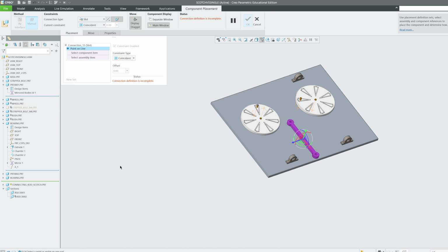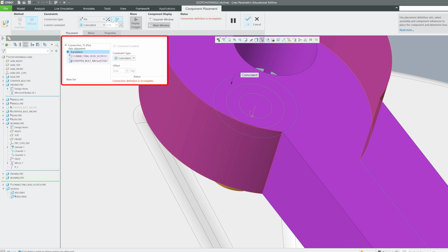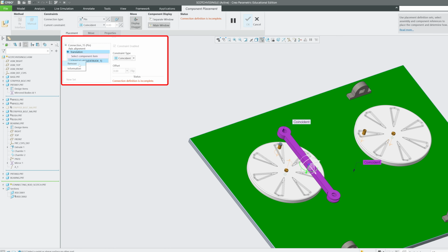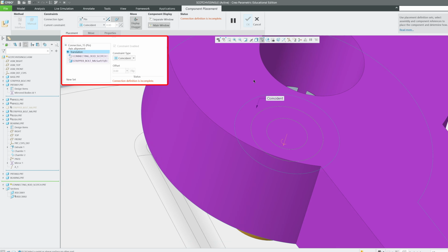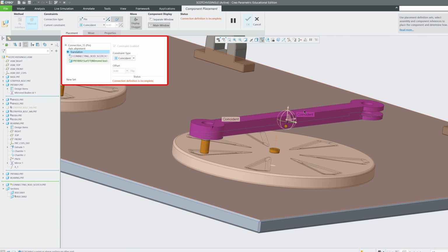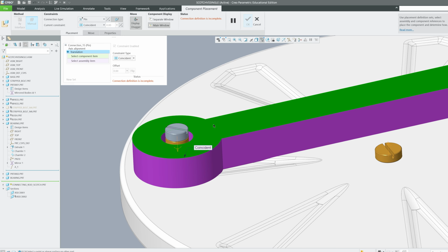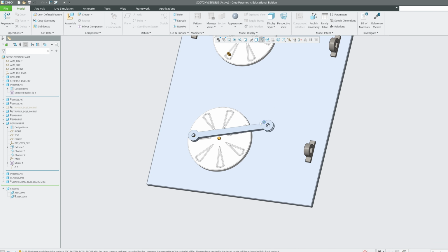So that's perfectly fine. Of course, I need to change the mechanism here, and I'm gonna go pin joint here and like this, but in the opposite direction. Yeah, I don't know why this jumped off. Yep, let's select the base, this one, and component. All right, so I don't know why this is not going down. It should actually go down perfectly fine. I need to make some adjustment here, I guess. Component. Oh, that's why. Now it is fine. Yep, so this is my pin joint like this.